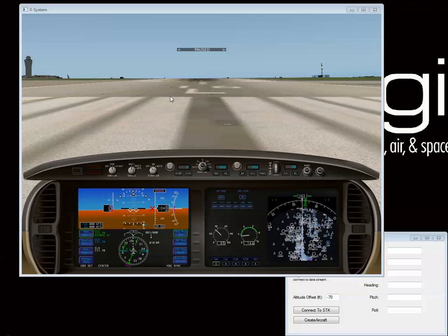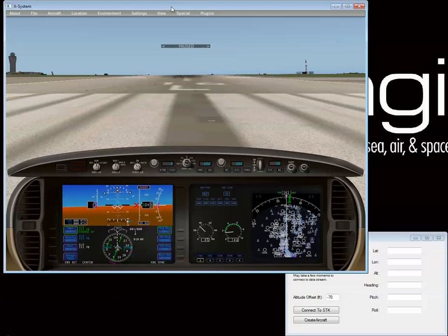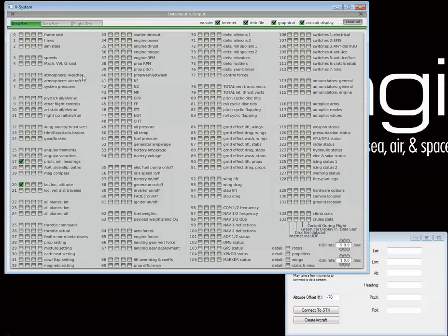Okay, this is an example of integration between XPlane version 10 and AGI's STK Systems Tool Kit version 10. Here you can see I've loaded up XPlane, and I can go to the settings and show that I'm actually outputting pitch, roll, heading, as well as latitude, longitude, and altitude. I'm broadcasting that over a UDP port, and I've maximized the broadcast rate, 99.9 packets of information per second.